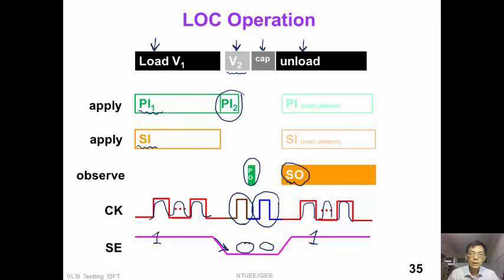So we can see that the launch on capture operation creates a transition by the first clock and captures the response by the second clock. So somebody also calls this the double capture technique.